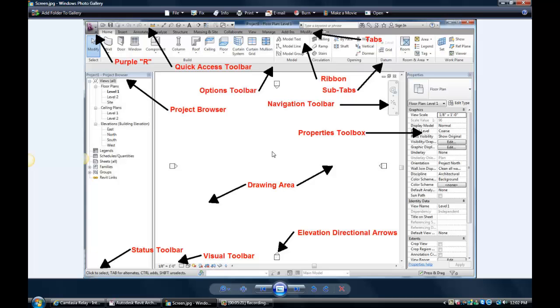But what I would like to say right now is, with the standard Microsoft mouse, where the left hand button on your mouse is the pick button and the right hand button on your mouse is the enter button, the roller button on your mouse works like a zooming feature. And if you pick and hold down on the roller button on the mouse, it should pan the screen.